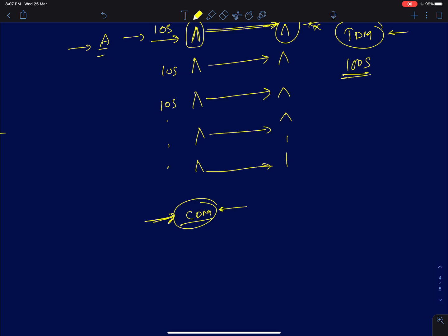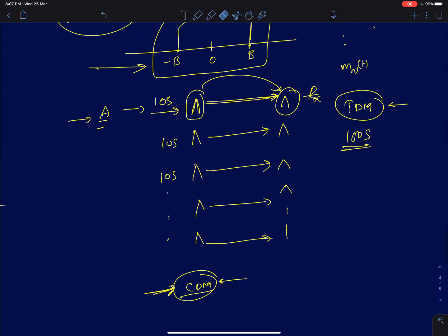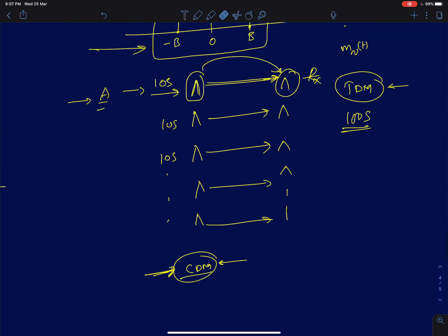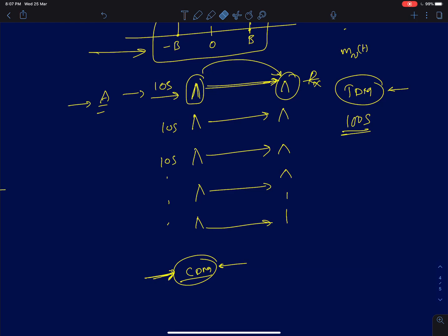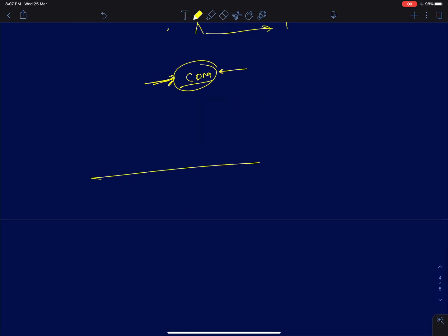The third one is that maybe different people can talk in different frequencies. You can change the pitch, the tone of your voice, and then maybe you can still hear it out. If two people are able to hear only one particular frequency, then they both can talk using high-pitched voices. The other guy may be sensitive only to low frequencies, so they can use a low-pitched voice to talk to each other. That's called frequency division multiplexing, which we'll come to in a very brief moment. So I just started with the problem, and said that the main problem was when you're upconverting data; one of the main reasons why we said we will upconvert the data is because we wanted to have realizable antenna sizes.